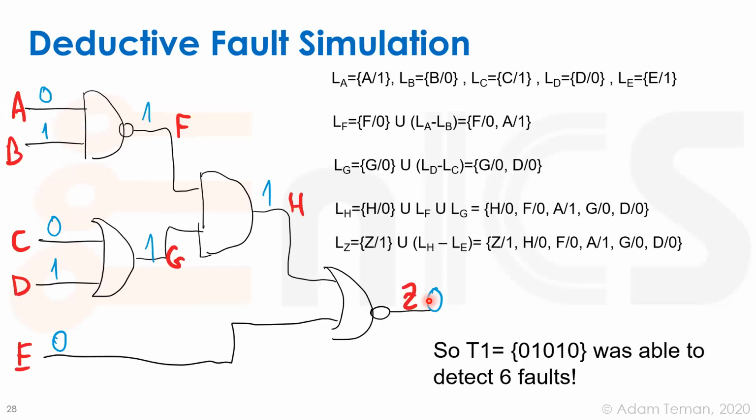Then there is an analysis process where you try to pinpoint the gate or the transistor which might be causing the issue, because maybe it's something in the design and not in the manufacturing, because it's not a random failure. It's happening all the time. Maybe it's some weak transistor or something which looks like a defect, but it is really a design issue that you didn't catch in verification.